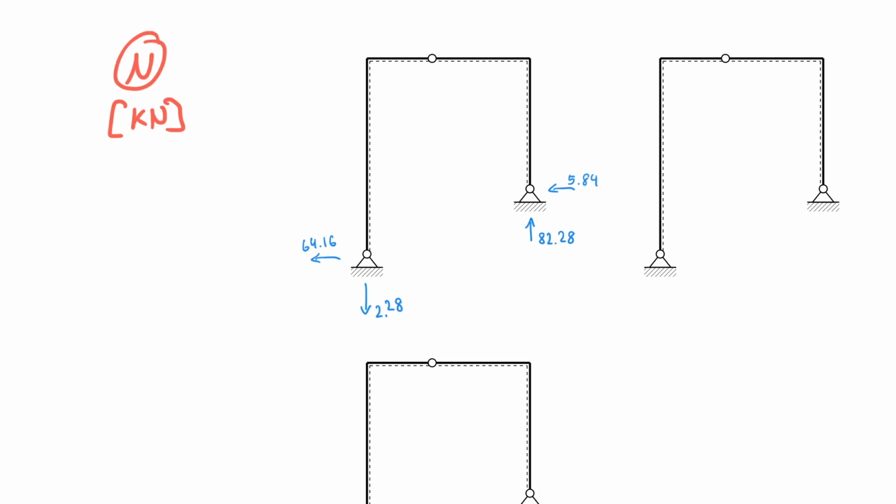So in member 1, on the vertical left part, the only thing that acts in line of the member was the vertical force. And see that here we have 2.2 pulling downwards. That means that this entire member must be in tension. I don't even have to make a cut to do that. I mean, a beginner should always make a cut, but I can already see that there must be a normal force that is in tension, and tension is positive.